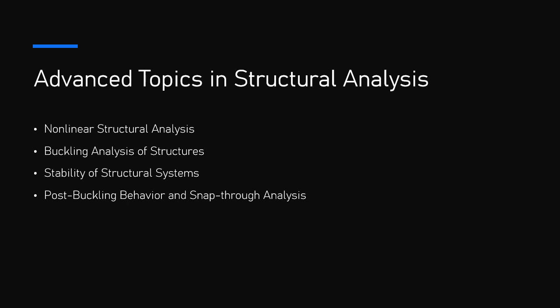2. Energy methods in post-buckling. In post-buckling analysis, energy methods are often used to assess the system's behavior. The strain energy stored in the structure before and after buckling is compared, and the system's potential energy is minimized to find the equilibrium configuration. The structure's load displacement curve is used to describe how the load carrying capacity changes in the post-buckling region. The curve typically shows a load drop after buckling if the behavior is unstable, or a load increase if the structure can continue to carry additional load.